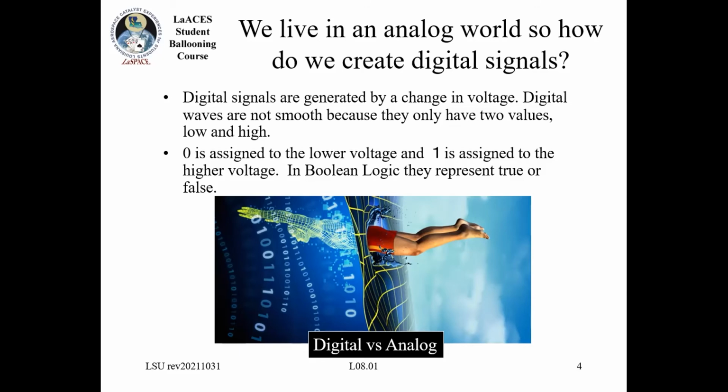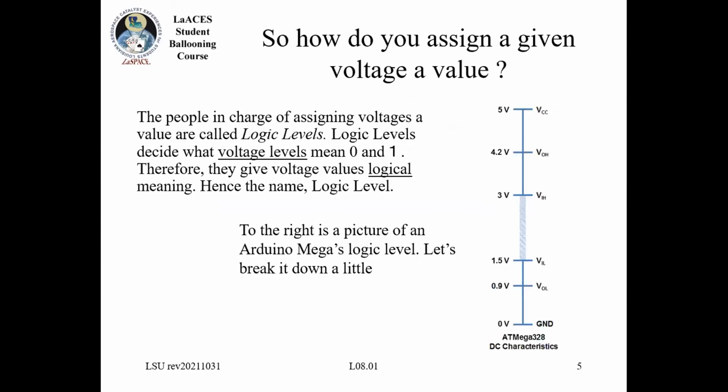So, like we said, digital signals are where you're having discrete changes in voltages. They're not smooth. Often you just have two values, a low and a high, if I'm talking about logic, right? Where my 0 and 1, or a true and false. So one thing that's important when you talk about any sort of digital interface is you have to define what the levels are for that high and that low.